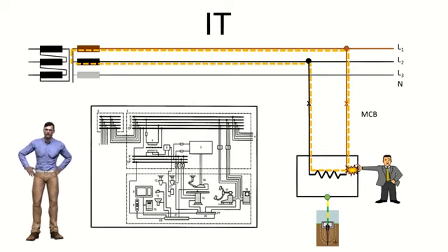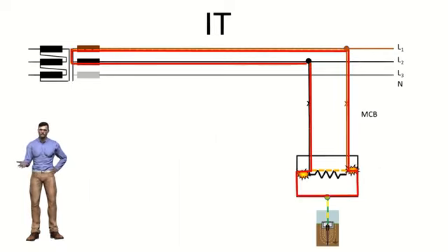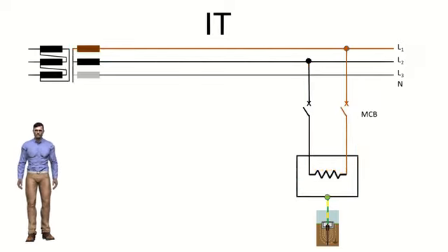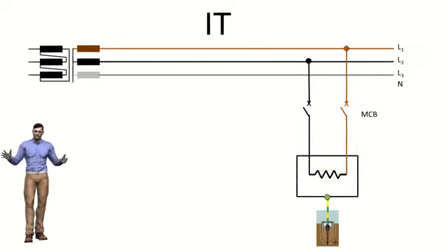Residual current devices or RCDs are not used in this type of IT installations generated by an isolation transformer. A second failure of another phase with a metallic envelope would cause a short across the chassis between the two failed phases, which will cause the overcurrent and short circuit protection to trip.